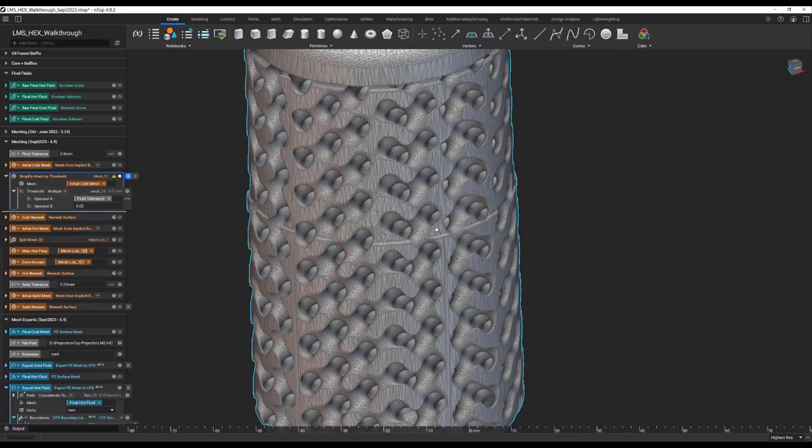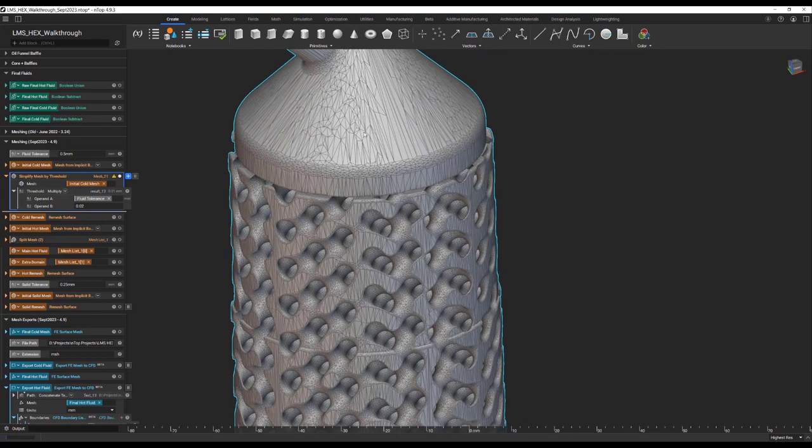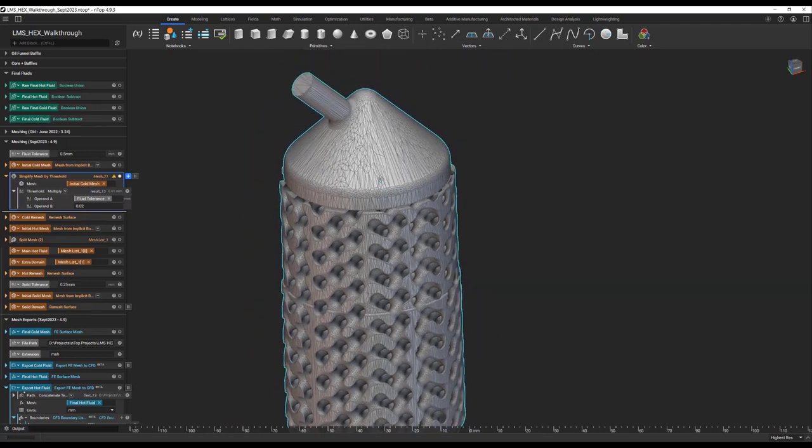I have experienced some issues trying to remesh these types of meshes, primarily just because the elements have poor orthogonality and skewness. And it also kind of then impacts the seed elements and sizes and faces during remesh stages. For the most part, I tend to stay in the remesh surface realm, but do know this is still a good option.